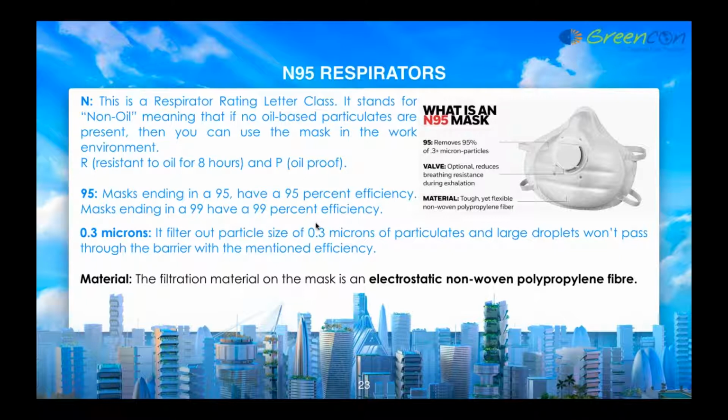Now we all know that a HEPA filter requires a lot of static pressure. How can a normal person wear a HEPA filter and still continue to have reasonable, comfortable movement? Well, the fact of the matter is the material being used in this is electrostatically charged non-woven polypropylene fiber. When you use this kind of material to withhold the particle, it is not because of a sieving action or the air velocity or all those things that we discussed a few minutes ago, but because it is electrostatically charged. So smaller particles have a higher chance of being attracted to it and retained. And that is the reason that it has limited life.